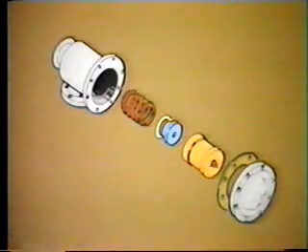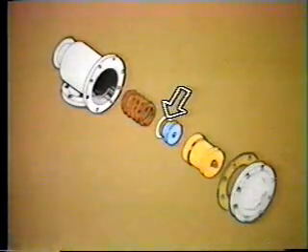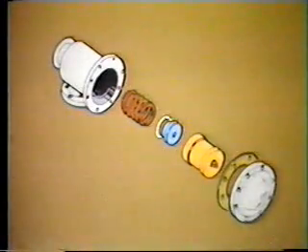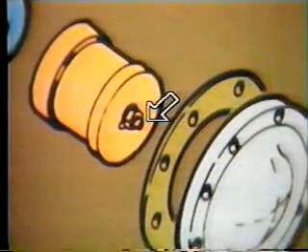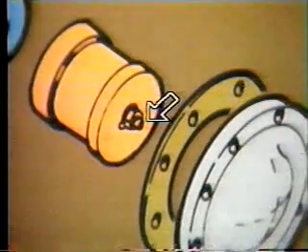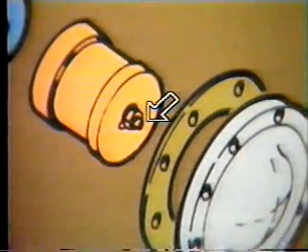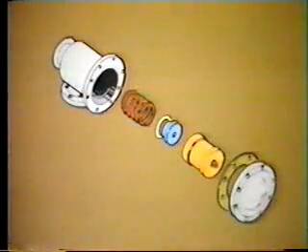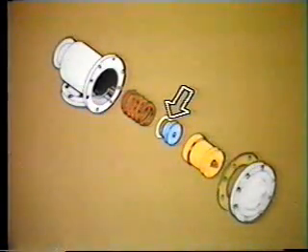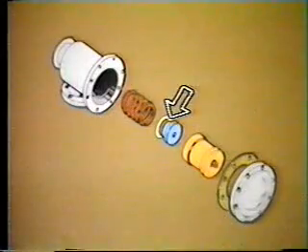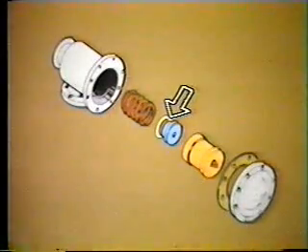Adjustments of the valve include the number of altitude shims used and the spring tension adjusting screw. The spring tension is factory adjusted and should never need adjustment in the field. The altitude shims were adjusted during commissioning by a factory representative and should not require any further adjustment by you.